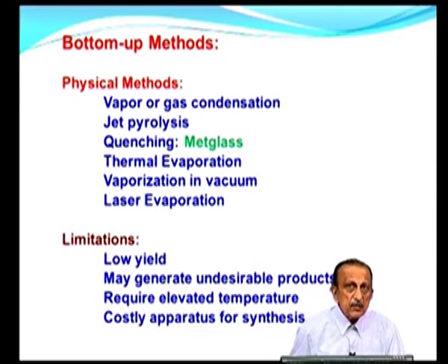One of the things to remember, which I am not sure that I alluded to earlier, is that nanostructured material, nanocrystalline material, that is, whether it is formed by a physical method or a chemical method, as long as it is a bottom up method as opposed to a top down method, where for example, one uses ball milling to cut down material to very small sizes. In such cases, as we mentioned at that time, defects are induced.